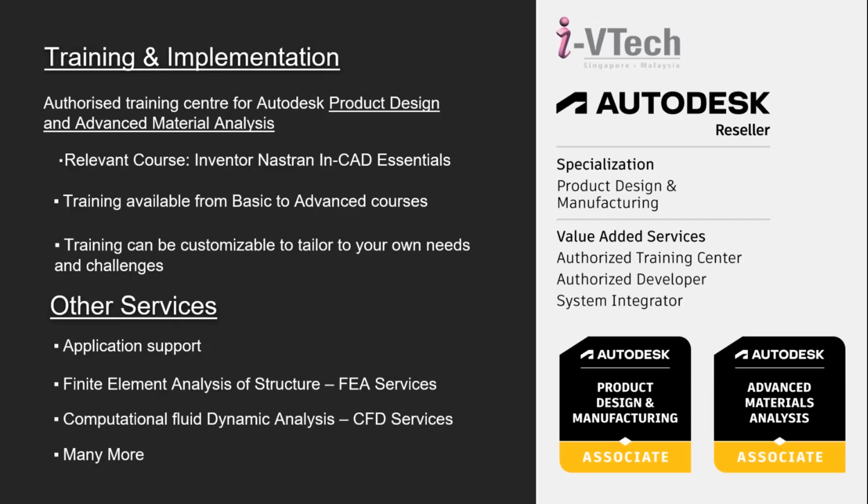Okay, one question: basic stress analysis in Inventor is unable to perform on structure members with thin thickness. Is it possible now in Nastran? Yes. For standard Inventor Pro simulations, for thin thickness, especially for structure members, usually there is a little bit of an issue. It can't perform simulation on something too thin, but it's now possible to be solved within Nastran.